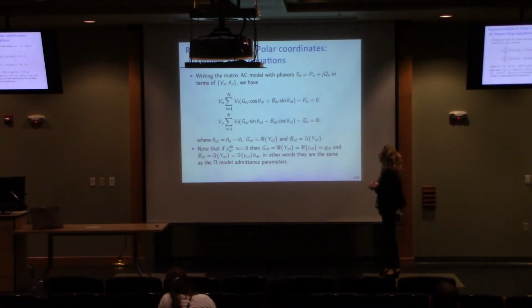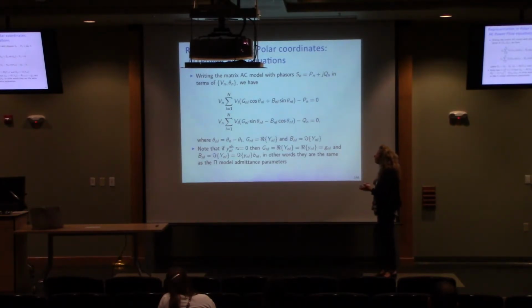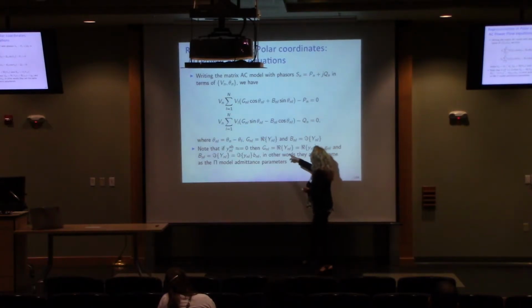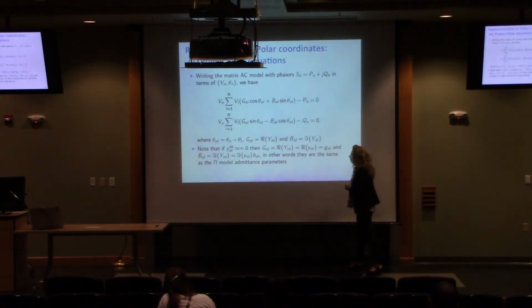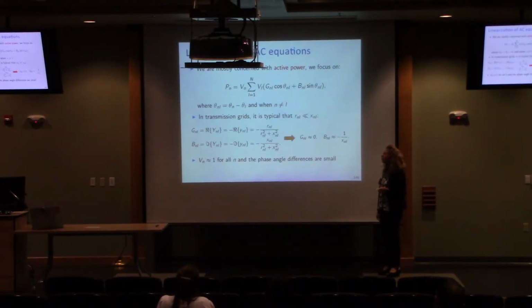These are the constraints for the particular relationship between voltage and current, real and reactive power. And then from this, obviously if you have the voltage, you can infer what is the current, and you can ensure that you are not exceeding some thermal limits. Okay? And so B and G are simply the real and imaginary part of this Y matrix. Okay, so most of the times you are concerned, as I said, about active power, because this is really what decides the set points of this generator.